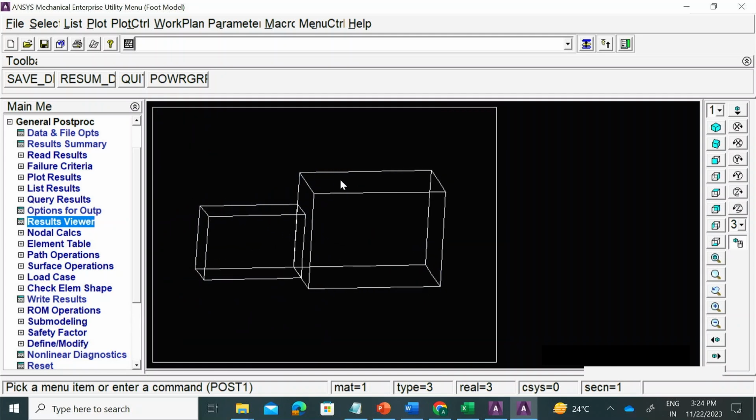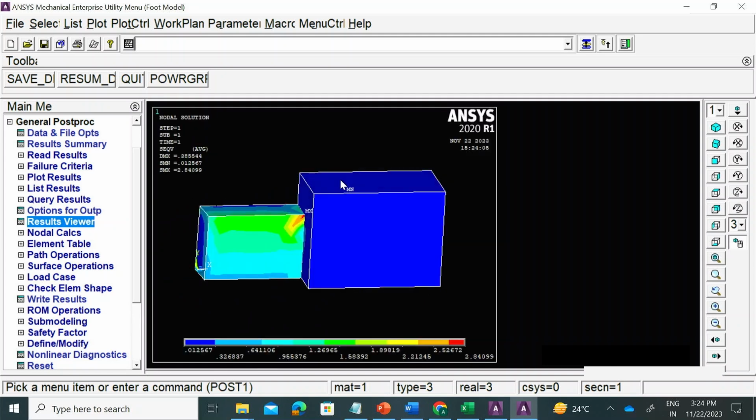So this is model number 1, where I wanted to show two bodies just touching each other visually and coordinate wise, with no interactions between them, and how to use a contact pair to create an interaction. We ran into one flaw where there was a little bit of overloading, due to which the contact condition was violated, and that's why we got a solution error initially, which was solved by fixing the loading.